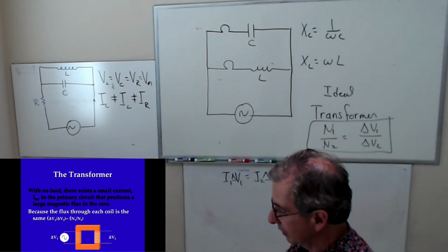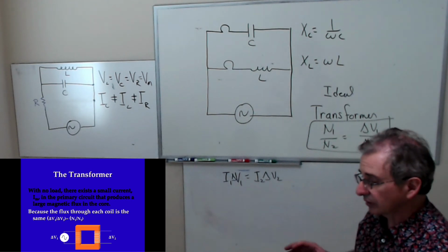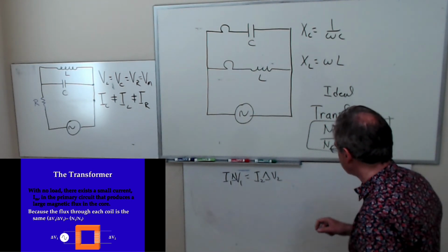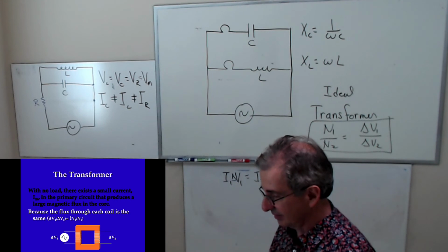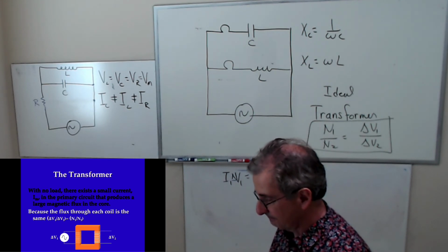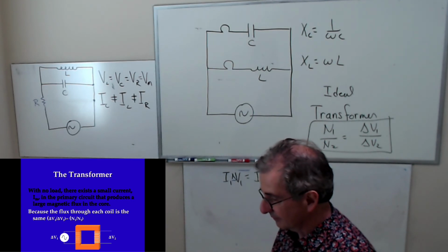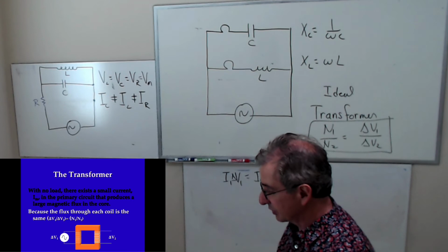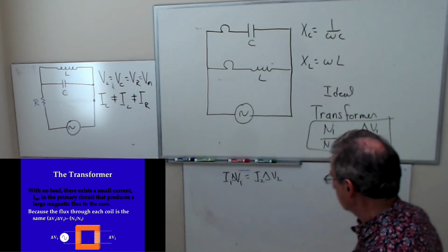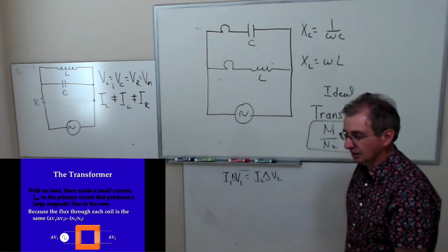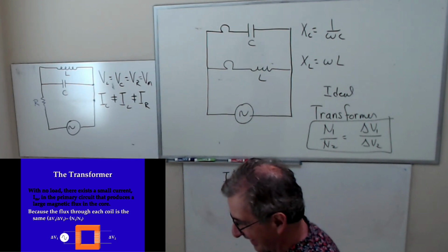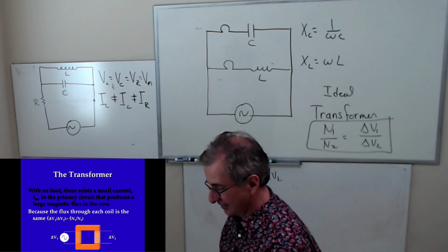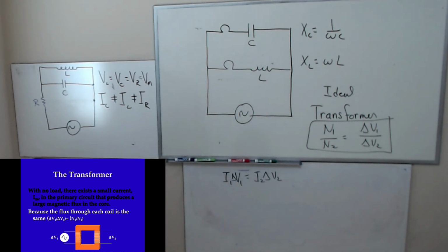In the picture you see there, there's no load connected to V2, so there's very little current on the primary side. But guess what happens when I connect a load to V2? If I connect a resistor across V2, you're going to get a current, right? You get more current in V1. Let me demonstrate that for you in a video.